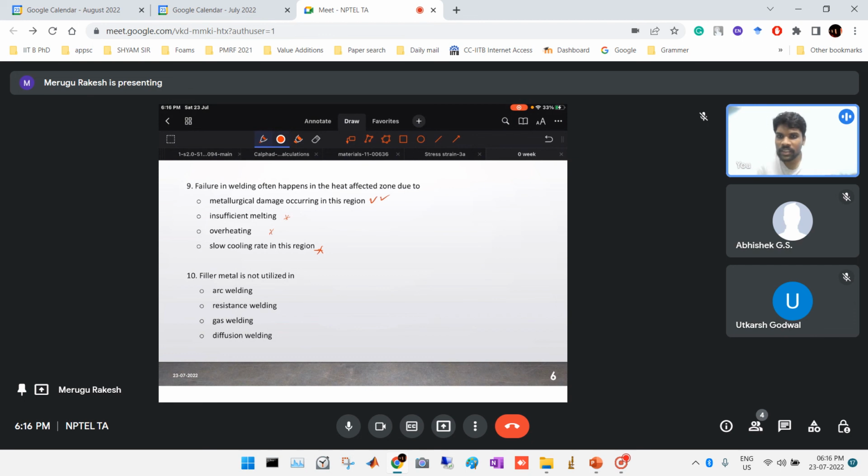So the final question is, filler metal is not utilized in. This is a contradicting question because of option C. Arc welding, so definitely we will use filler metal. Resistance welding, I will keep for some time. The next one is gas welding, we use filler metals there also.